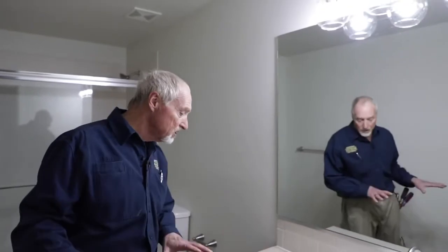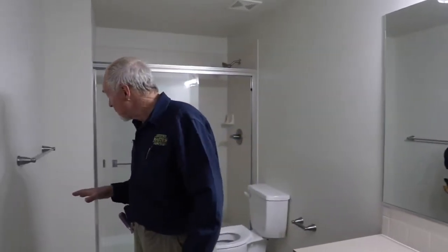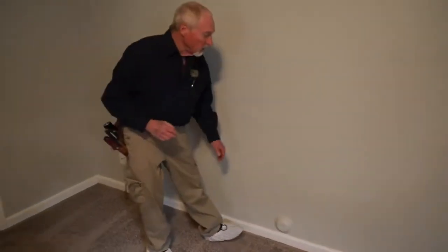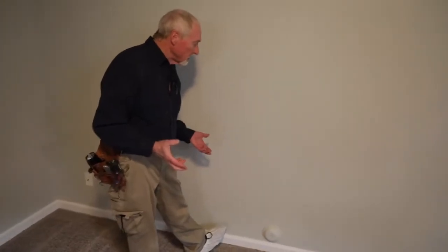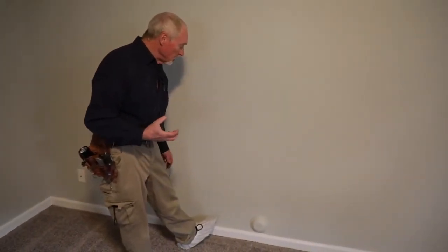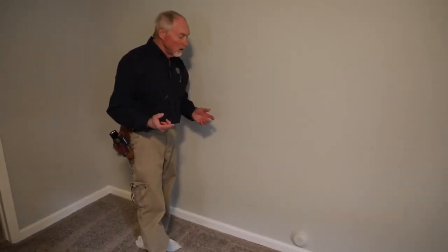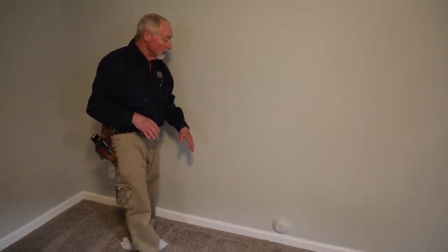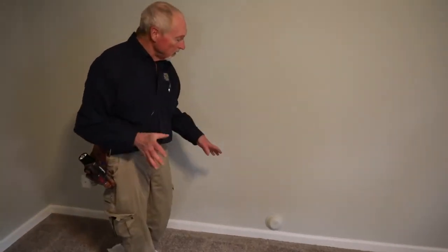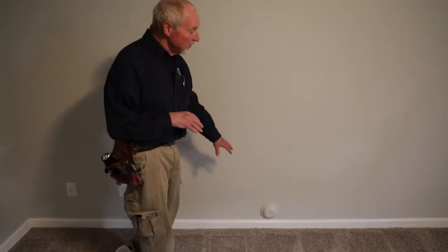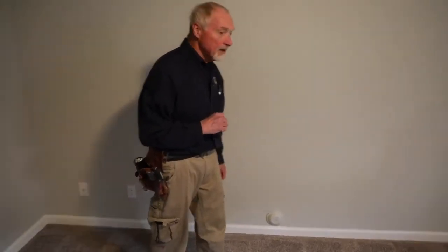So that concludes this bathroom, and we have some more bathrooms to check also. So while we're here in the basement, we have this little cover here. This is, again, almost certainly over a clean out access point into the DWV drainage waste vent system. Clean outs must be accessible, and so this is what we like to see. It's better than just having a hole in the wall. Again, no requirement to take that off, take a look in there. Just you understand that that's what that is, a cover for the clean out access. And we have probably some more around in the basement as we go around, but just letting you know that's what that is.